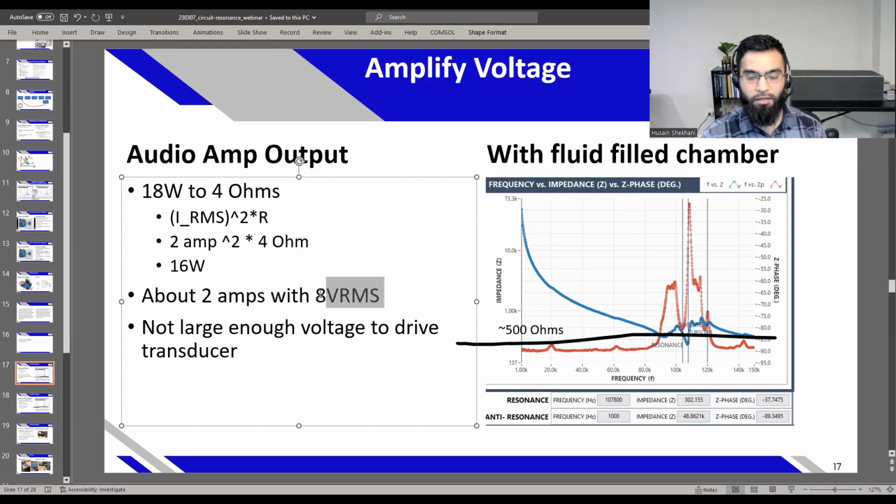And I've got to let you know that the 7-volt battery that I have is not going to be able to drive an 8-volt signal from the amplifier. Amplifier means amplifying the signal input. It doesn't mean amplifying the voltage supply input. So if you buy an amplifier, you're only going to get as much voltage as it produces internally to supply it.